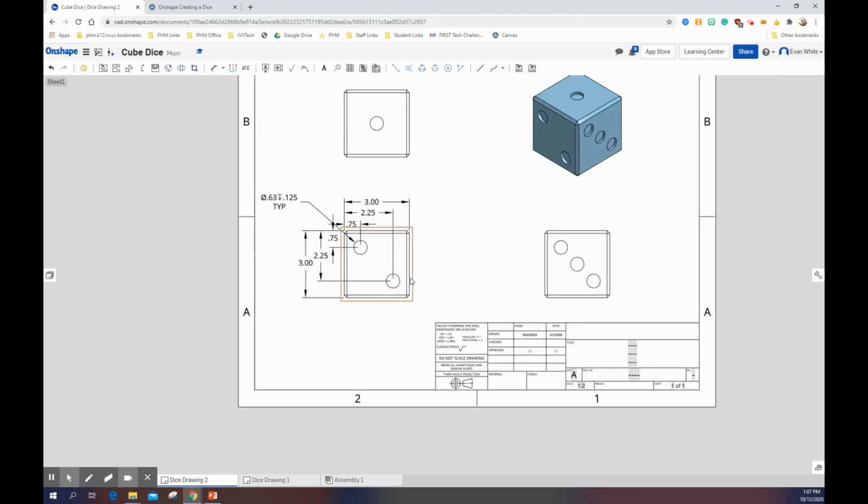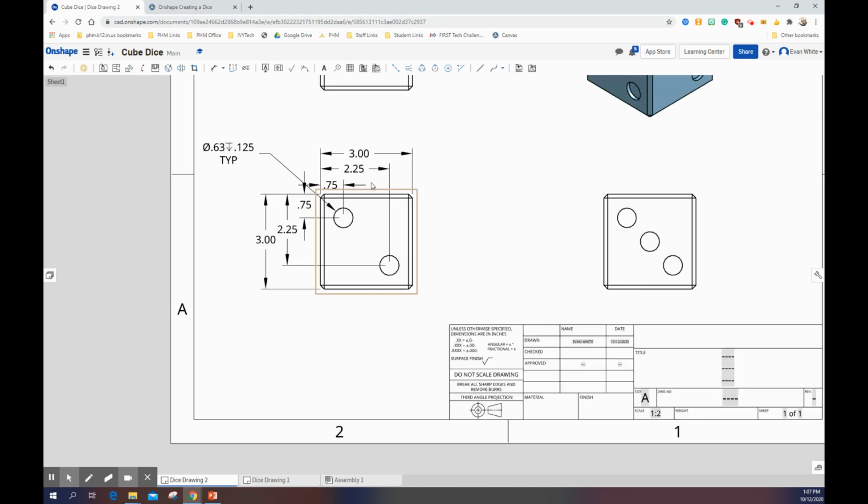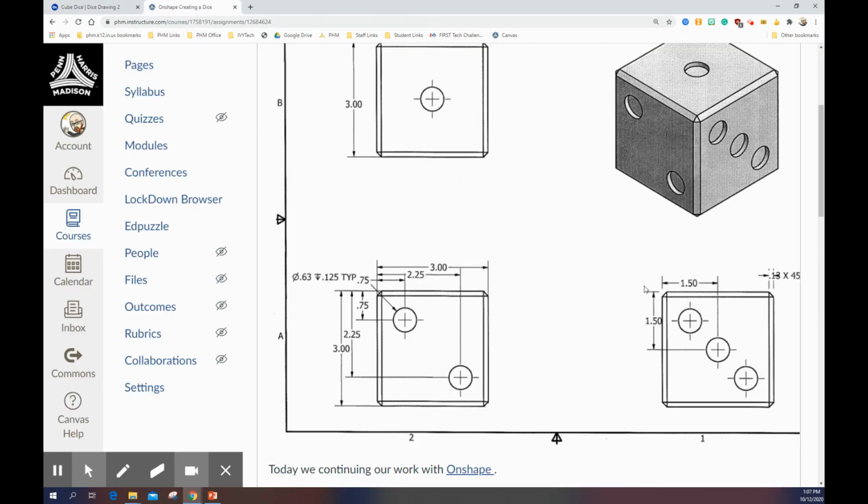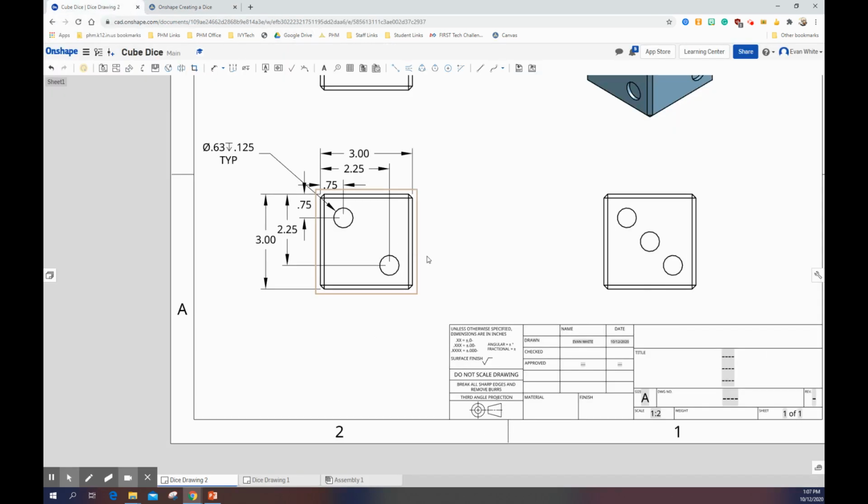Other things that are on here are a lot of center holes. Well, how do you do a center hole? How do you actually mark it? If I look here, this one's done. I just need to measure these two out. But they have these center holes here. Oh, what's that? Well, like this. You go to your drawing file. I could put a center on each of these circles by just clicking on it like this. But I think more accurately is a center line. If I hover over this 2-point center line, I can click the 2 sides of it.